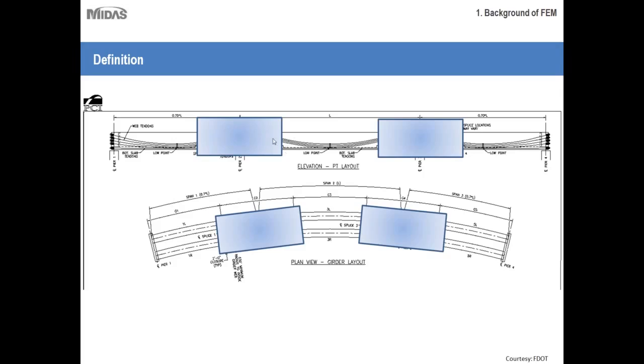In these zones you have to apply the lid slab on top to cover the U-girder opening and provide enough stiffness to the section to avoid any kind of torsion in the segment and give it its stability. Because after this stage we will be doing the post tensioning and applying the deck slab on top of it.